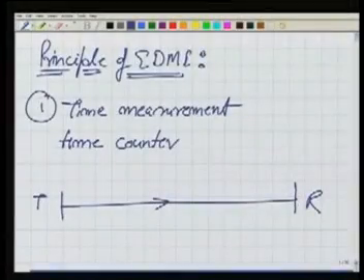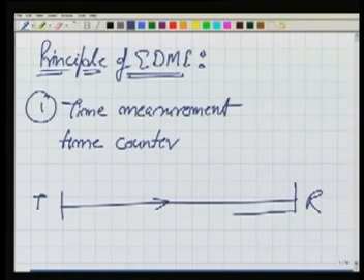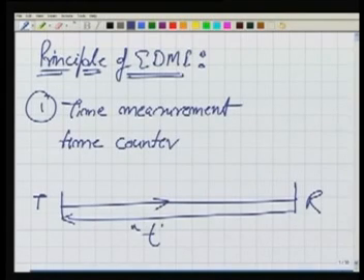So the pulse travels to the reflector, and then from there it comes back. Now somehow this time of travel is measured. Now how is it measured? There are various devices. Basically it's a CCD based device, charge coupled based devices are there, or photodiode based.